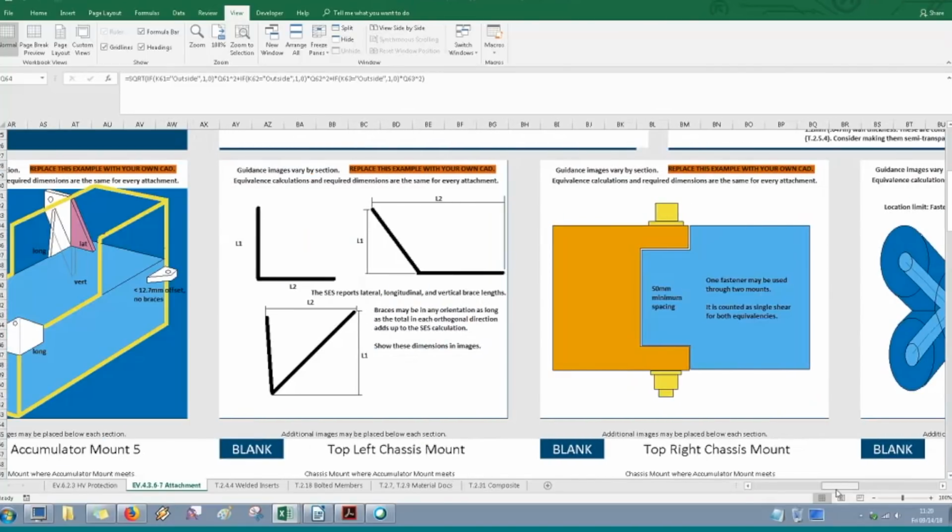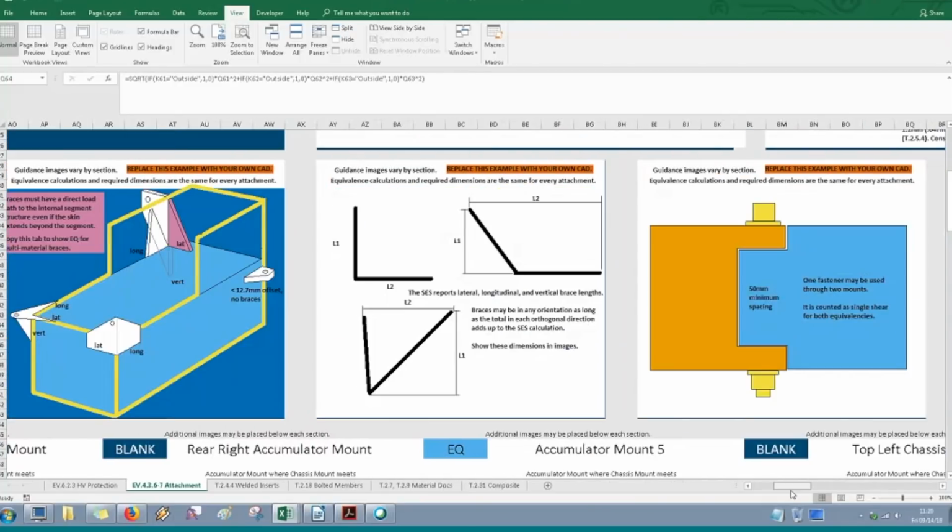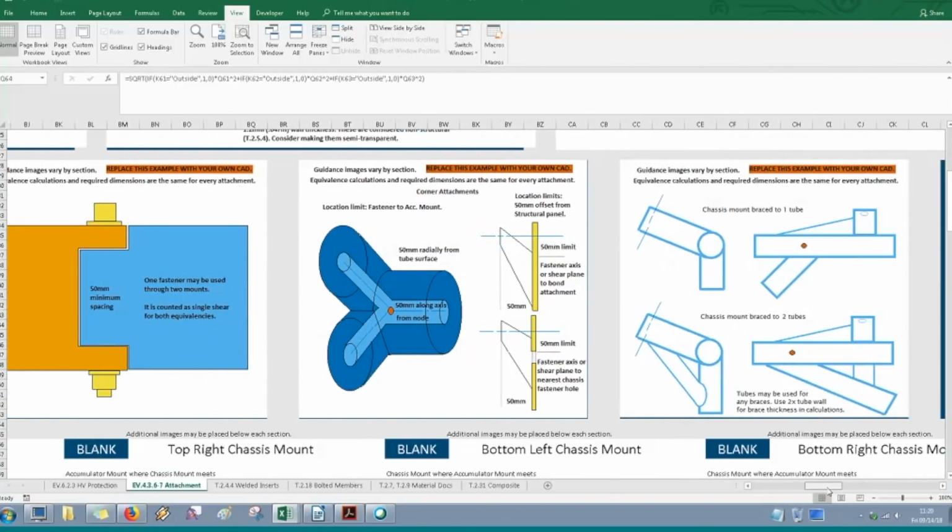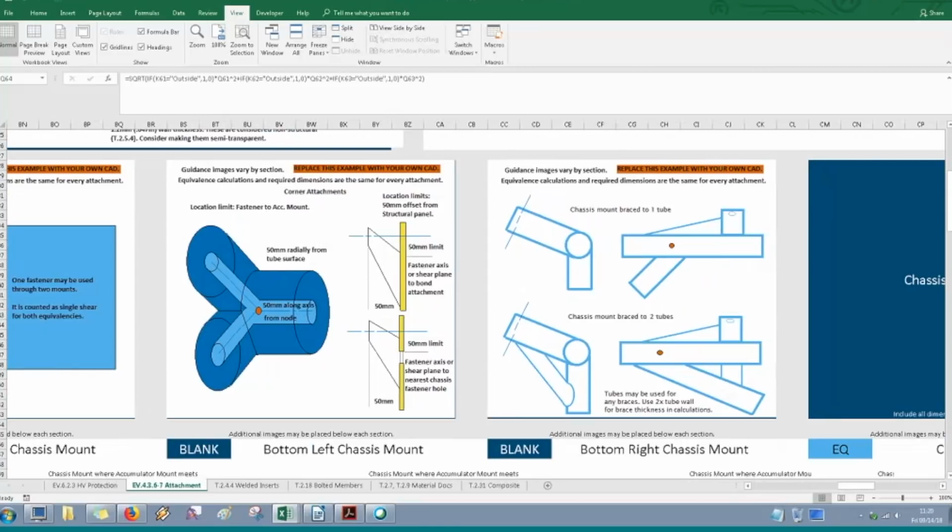Another thing that hasn't been mentioned yet is the idea of having a subframe. If you wanted to run a subframe directly to a mount on a monocoque or a hybrid car, and then build it with some nodes that'll meet this same requirement as if it were a tube-frame car, and then run your pickups to there, that'll be completely fine. Make a copy of this attachment tab and repeat all of the math to make sure that all of those places where the subframe attaches to the monocoque or the hybrid are just as strong.